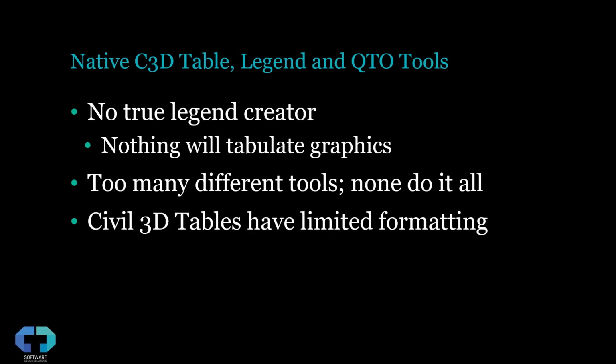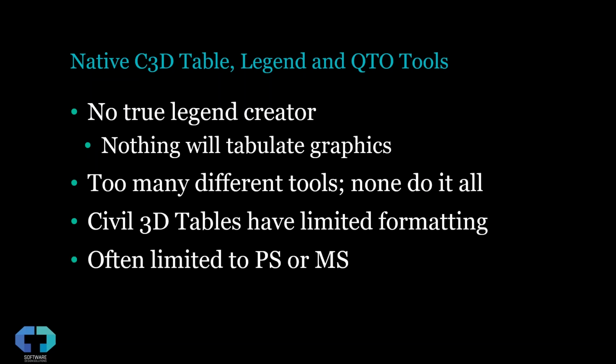The Civil 3D tables, those of you guys who have used them, they're great. They're dynamic, right? They scan what's in the drawing, but the formatting is really, really limited. A lot of manhole schedules people are trying to generate. You can't quite do it with the Civil 3D tables because the formatting needs to be fairly detailed.